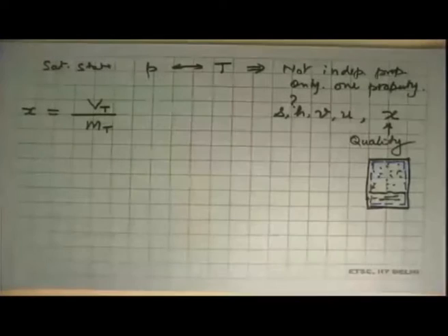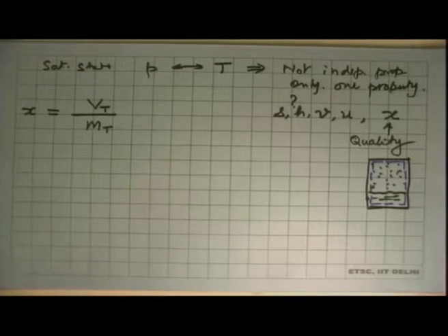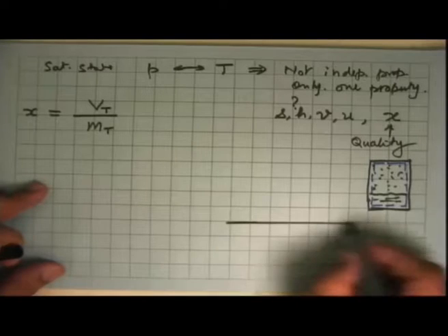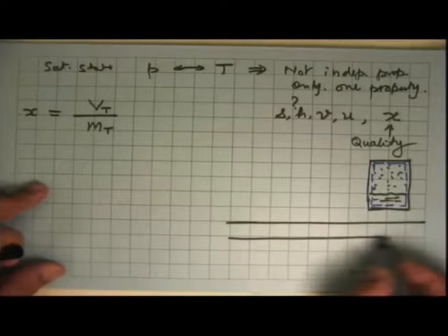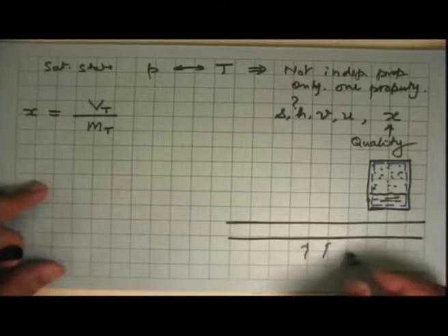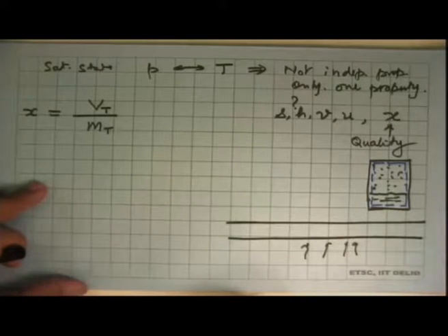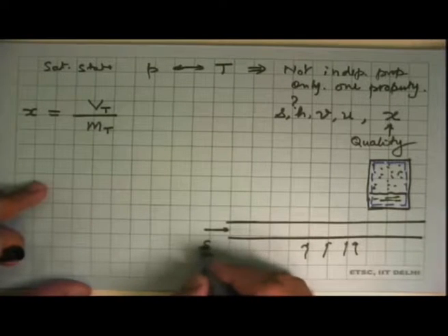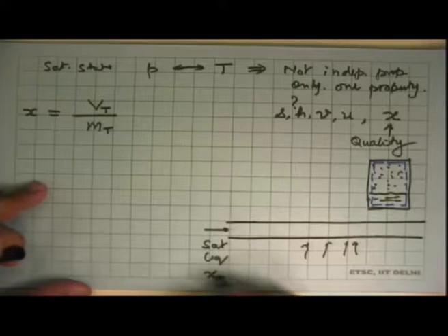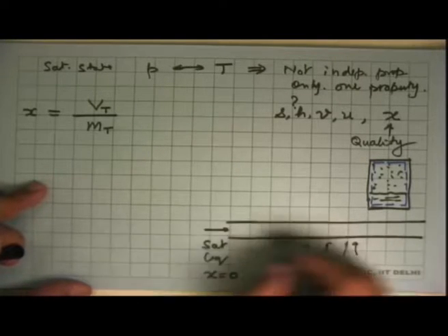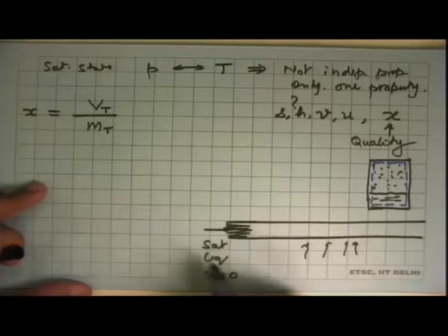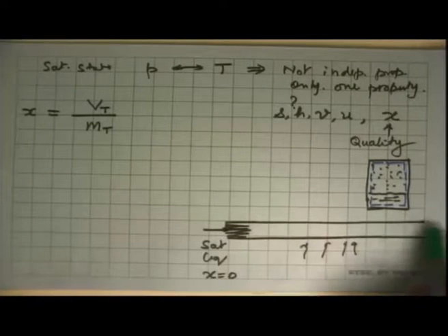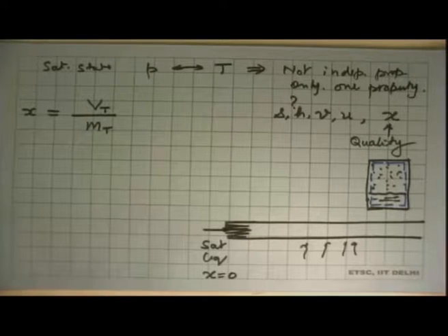It's not necessary that this is the only way in which a liquid and a vapor in a saturated state can exist with one another. Another example is a tube which is being heated, like the evaporator of a refrigerator or evaporator of an air conditioner. At the entry of this, we put saturated liquid. Dryness fraction is 0. And we ask that the liquid was completely occupying the space inside the tube. What happens to this liquid as it gets heated and it flows through?